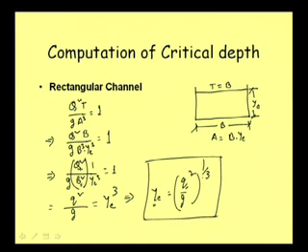Well, one important point, though it is obvious, it is better to mention. If someone asks that a channel is carrying this much discharge and it has this much slope, what is the critical depth? Many students think about the slope when asked to compute critical depth.